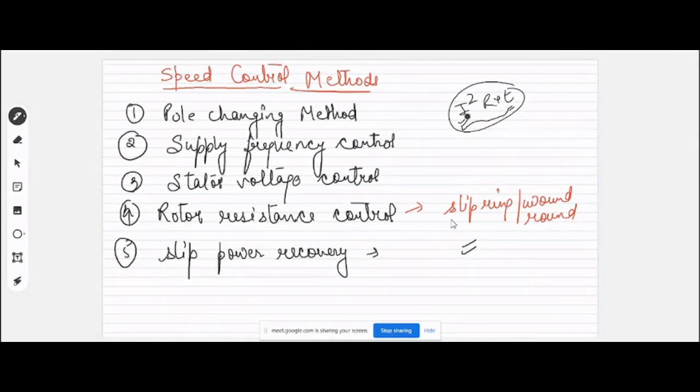So in those machines where the motor load system has high inertia, we have to use these starters because of this high starting current for a longer period. It may overheat your machine, and because of this overheating, your insulation may get damaged, because of which your windings may also be damaged. I guess it is clear to the class. Why do we use starters, right?